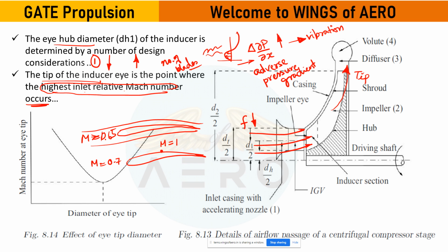At some point over the surface of the blade a sonic region will form, and gradually it will enlarge and it will cause shock waves. If shock waves are forming over the blade, then definitely shock wave means a pressure gradient is occurring over the blade. Now definitely it will lead to the damage of this blade, right? If the blades get damaged, the flow cannot be compressed as it is required. So again we need to design it very carefully.